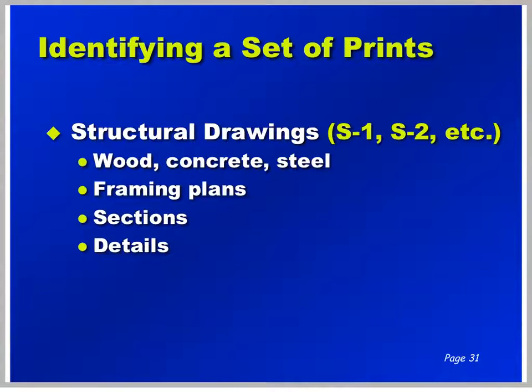Next in the set would typically be the structural drawings. The structural drawings are usually identified with the letter S, such as S1 and S2. The structural drawings are that portion of the drawings that identify the structural components of the building, such as concrete, masonry, steel, wood. It's what makes the building stand up.